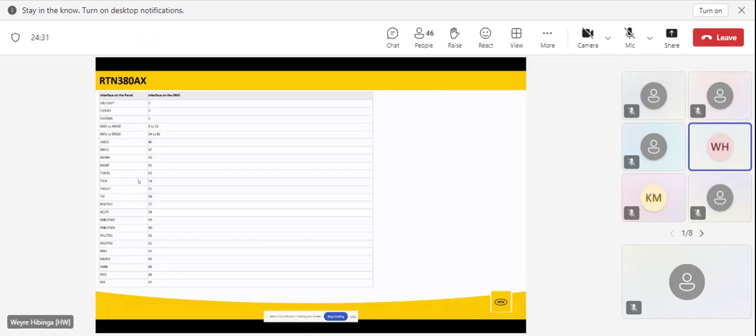Then DM1 to DM20, those are ports similar to the demultiplexer. You use this for demultiplexing. And then you have Mon R and Mon T. You can connect these to the spectrum analyzer or PM8. So Mon R is for monitoring the signal that is received from the preamplifier. Then Mon T is for monitoring the signal that is being transmitted out of the boost amplifier.